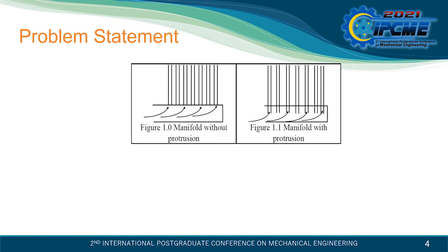Heat transfer in the microchannel heat exchanger is a function of the maldistribution of flow. The effects of protrusion configuration of microchannel passages on the flow uniformity have been numerically studied so far. In addition, resources are limited. The effects of various protrusion configurations and several geometric parameters on the flow uniformity can still be explored further.